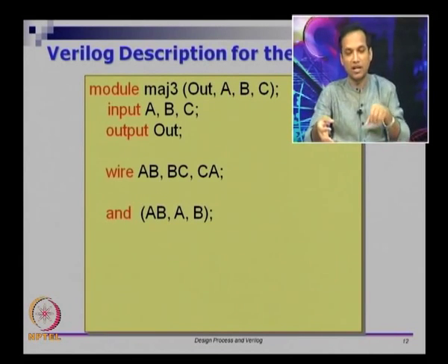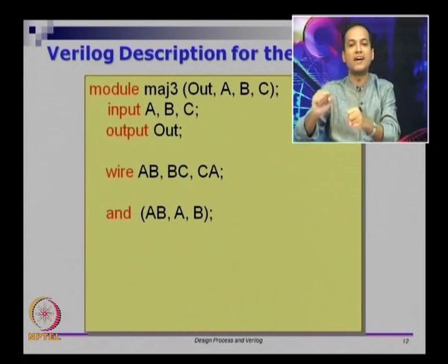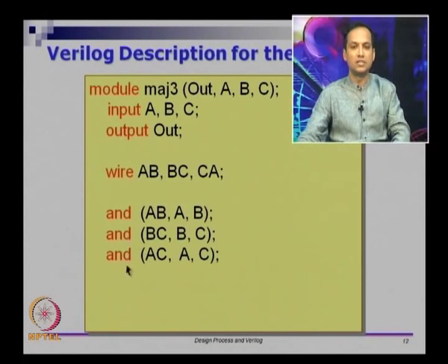You would go and pick an AND gate and put it on the breadboard. You will connect two inputs A and B to it, and wherever the output pin is, you will keep it dangling for a while, so you know you want to use this later. Then similarly you need the logical AND of B and C as well as A and C. Now there are 3 AND gates and the 3 output wires are dangling.